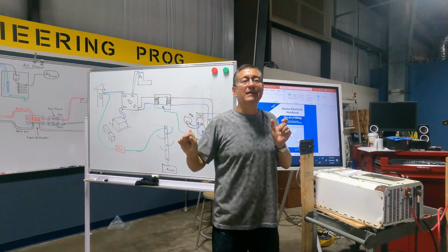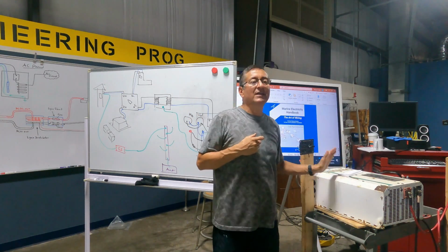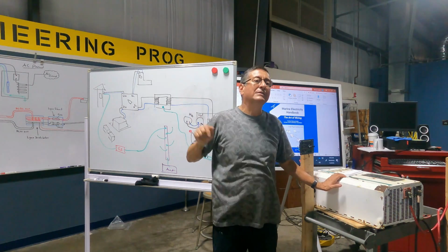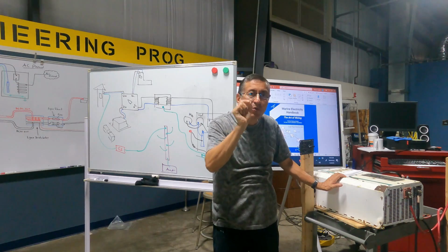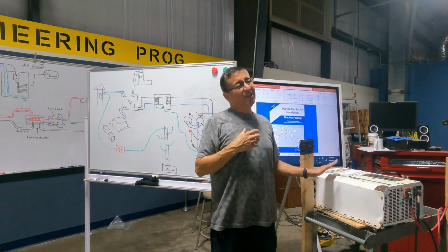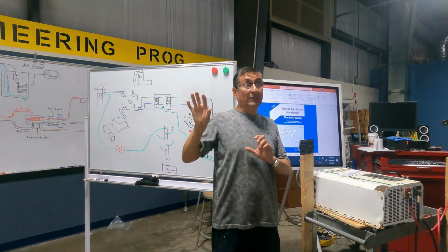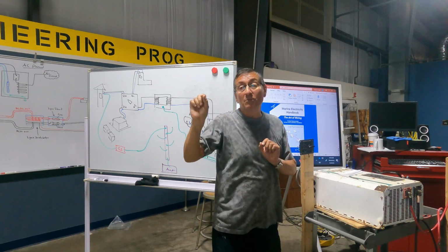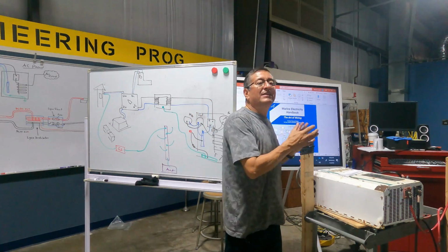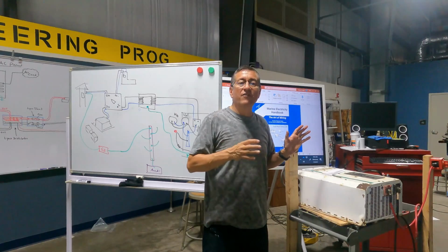Don't use this, this, and this, because the inverter is not able to support this, this, and this. Only the blue ones. The people put a mark, blue or red or whatever. You understand? Because those inverters are good only with the small air conditioning unit, not with the big one. In other words, the capacity of the previous generation of inverter is not perfect.